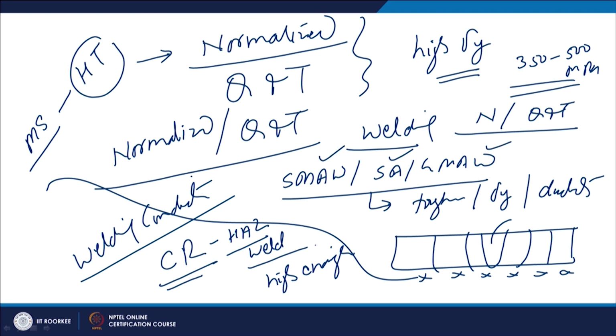The cooling rate is high enough to produce a fine pearlitic structure or low carbon martensite. So, this will not deteriorate the properties appreciably and will lead to a good combination of hardness, toughness and strength.